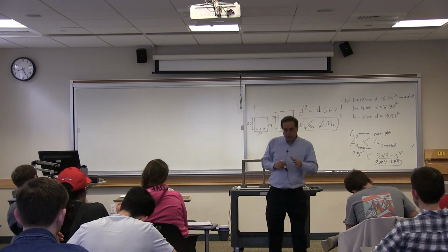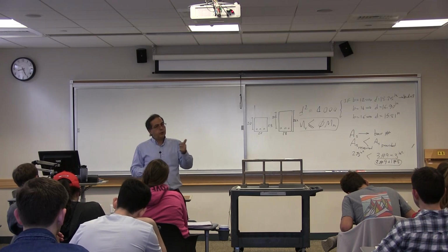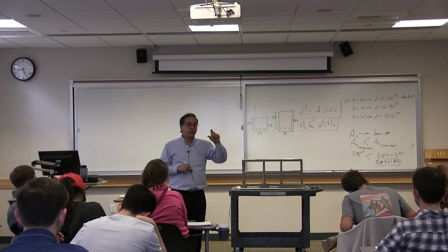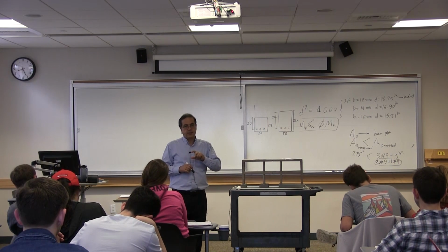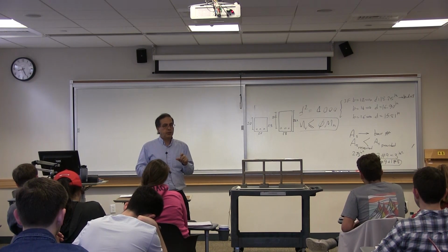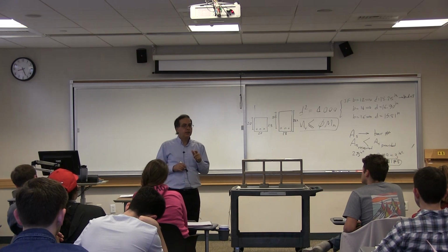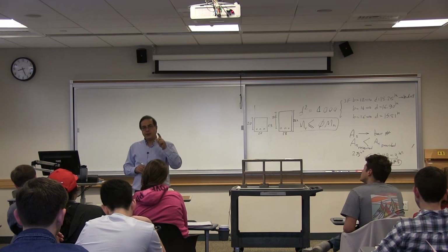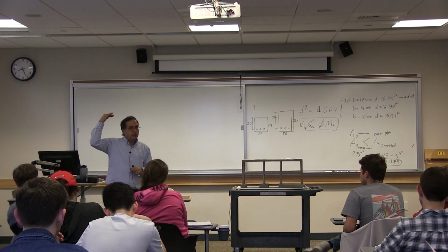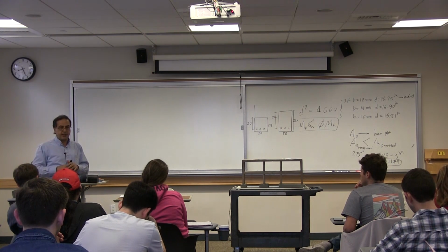Moment of inertia is important as far as deflections go. When we are designing, we don't design for deflection. That's indirectly correct, but when you design, you don't design for deflection. You design for forces. And when we calculated forces, we didn't use moment of inertia. Remember, why didn't we use moment of inertia? Because material properties at the ultimate level is nonlinear. You cannot use moment of inertia. Your answer is correct at a different level, but what is the more specific answer here? Linked to what you said.